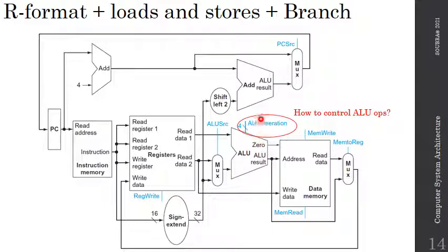So if this is a control signal and the control signal is made out of 4 bits, this means that I can select anything between a possible 2 to the power of 4 operations inside of my ALU. So theoretically, using the information that I have here, I have up to 2 to the power of 4 possible operations, so 16.